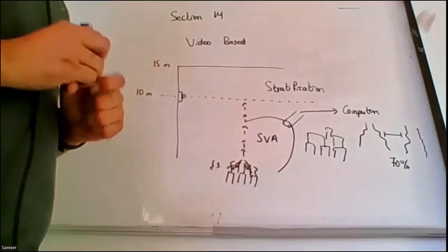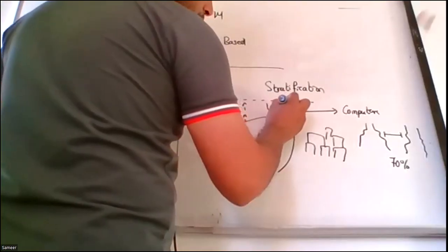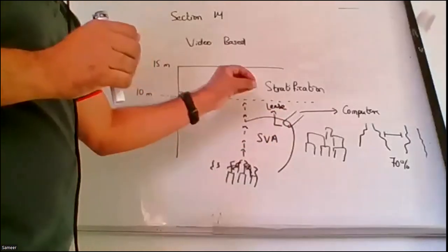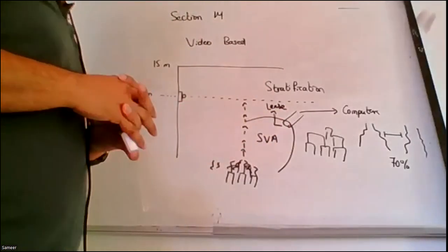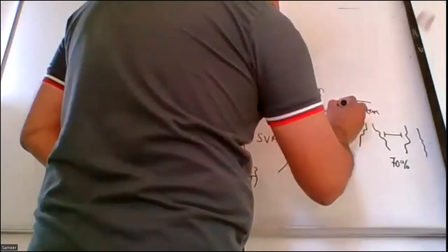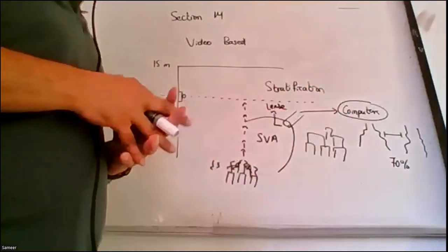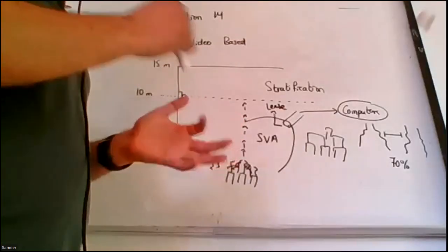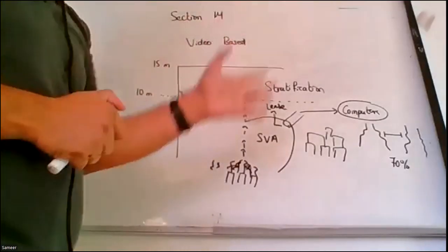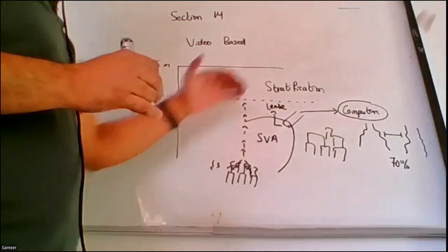Now the lens requires maintenance. Why? Any accumulation of water, dust, or any foreign material on the lens will affect the detection capability of the detectors. The second thing is that it requires more maintenance on the software of the computer. That needs to be completely checked. A health check of the system should always be there. It requires maintenance after every 2 months. The lens and the computer software, everything should be checked so that the detector shows its capability accordingly.